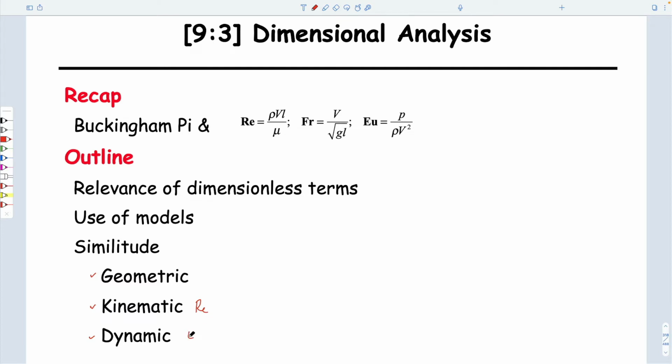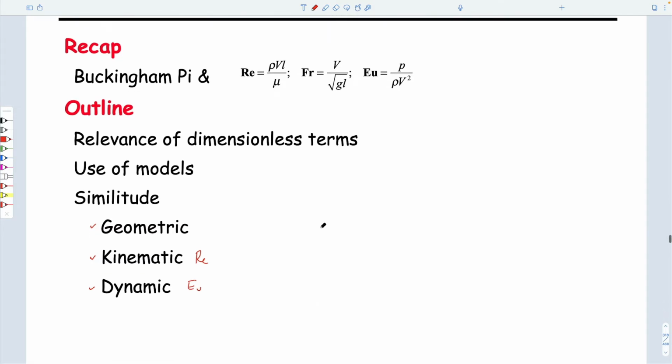This is Reynolds number, this is Euler number, and if we can define for whatever our system is what these numbers would be, they don't necessarily have to be these, but they turn out to be those typically. For any system you could use, even for understanding the financial markets or for any kind of experiment you want to do, dimensional analysis is an incredibly powerful way of doing it because it basically allows you to minimize the number of experiments that you do. And so I am going to do exactly this Buckingham Pi.